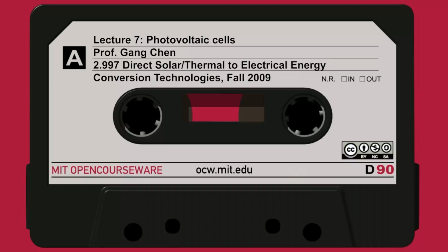With 1 over alpha in centimeters, here is about 10 microns. So if I use 10 microns, the energy below 1.6 eV is absorbed very little. It goes through the cell. It doesn't get absorbed. So if it's too thin, this part will go out.